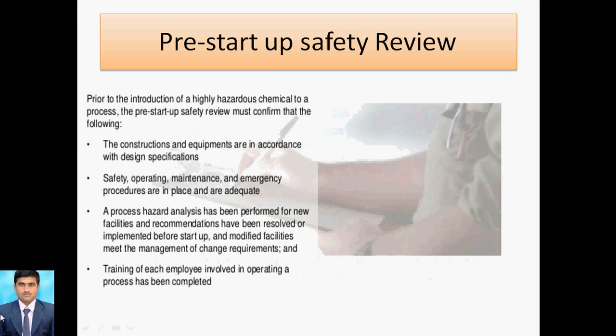Then pre-startup safety review. After giving the information to the operator regarding the highly hazardous chemicals, we review before start-up the construction regarding the design specifications, that safety, operating, maintenance and emergency procedures are in place, how the hazard analysis is done and how to start up, and that the training of each employee involved in operating the process is completed.